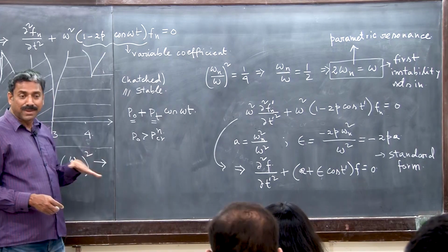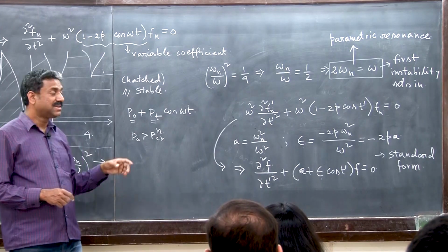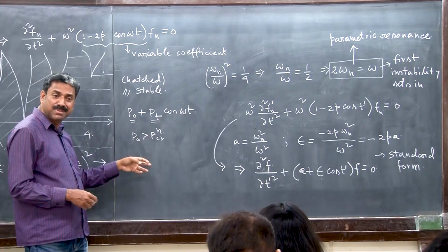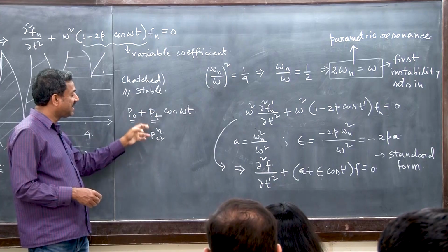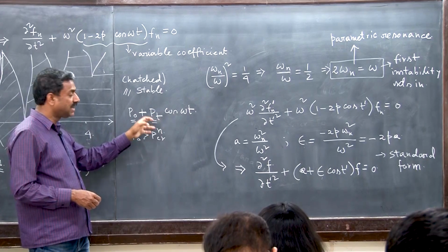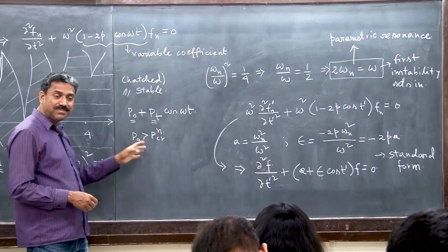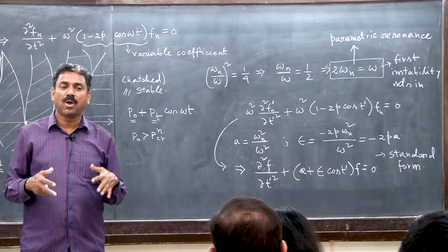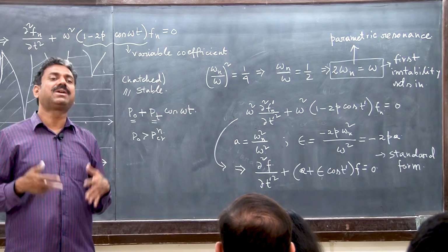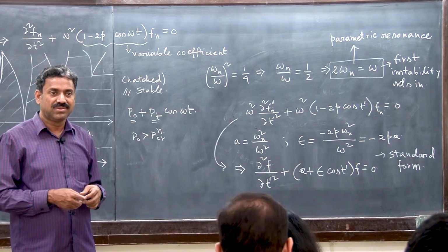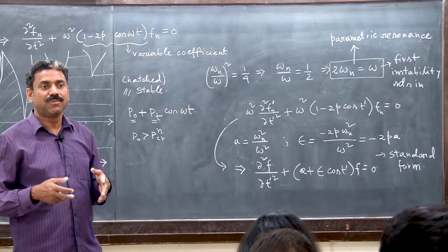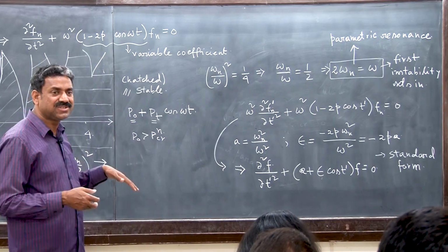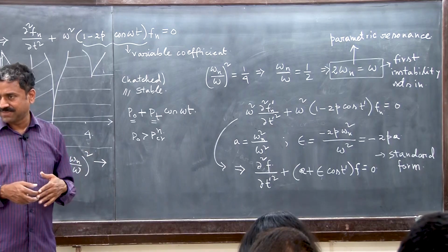Okay, when parametric resonance is occurring, even P0 can be greater than the critical load. But in addition to that, you are getting some component of dynamic load. So parametric resonance may occur at load beyond critical load. So the column can sustain a loading amplitude which is beyond critical. You understand that? Of course, a part of it is static and a part of it is dynamic.